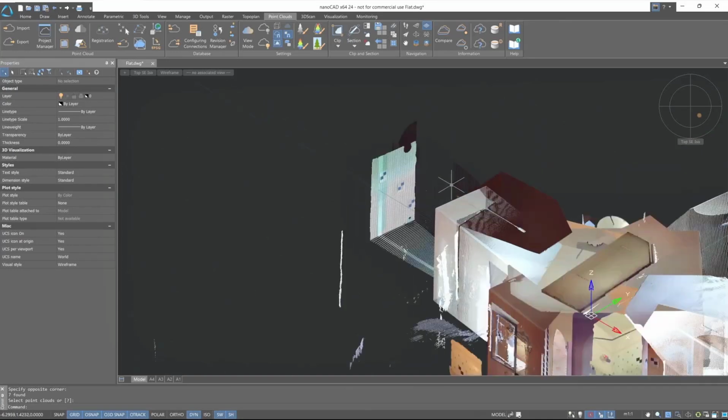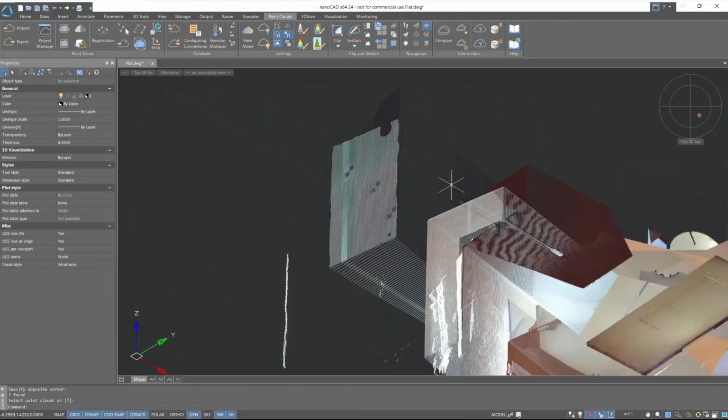Usually for simplification of alignment, so-called targets are used, objects that can be easily identified in the point cloud. By determining the centers of the targets in the point cloud in one way or another, we obtain the coordinates of reference points for subsequent registration. Reference points belonging to one scan are grouped into reference point groups.